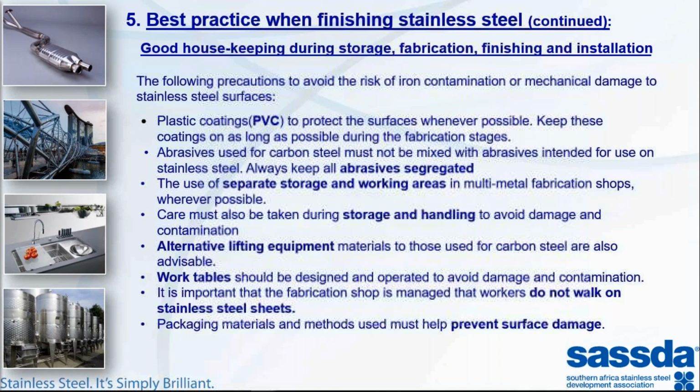But like in any stainless steel shop, whether it's industrial, architectural, or for high-spec industry, good housekeeping during storage, fabrication, finishing, and installation is extremely important. So the laser film, that PVC coating on your sheet metal to protect the surfaces, is important. Keep those coatings on as long as possible.